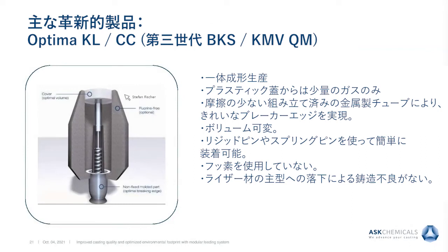By using different plastic lids, we can also create different volumes with the same riser. The application is very easy by using a rigid pin or a spring pin. Most of our customers today are using the maintenance-free rigid pins. Of course, as already mentioned, these risers are also available in completely fluorine-free formulations. And one important thing is that there are no casting defects coming from the riser material falling into the mold.